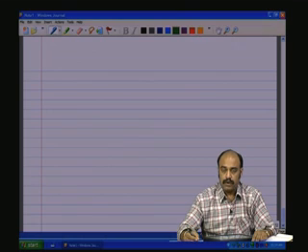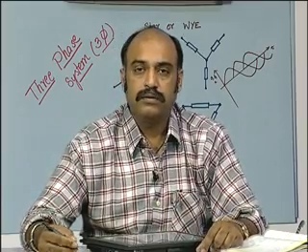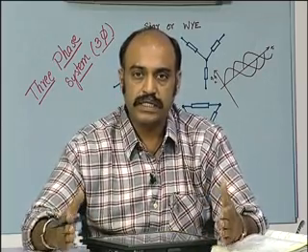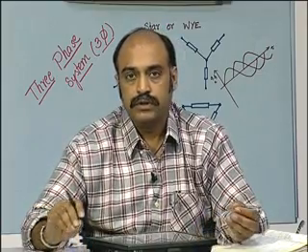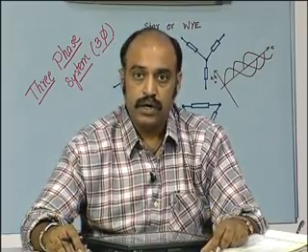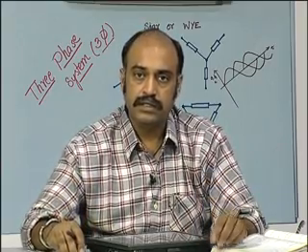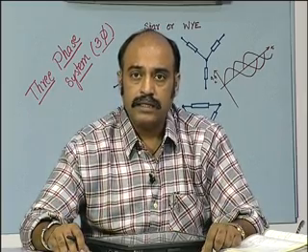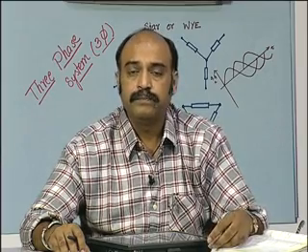So, in a 3 phase circuit also, you can have non-resistive loads. It need not be pure resistances, it can also be impedances, which means combinations of resistances and reactances, which means some portion of the power is going to be reactive in nature and some portion of the power is going to be active in nature. And the concept of the power factor that we developed earlier is still valid.